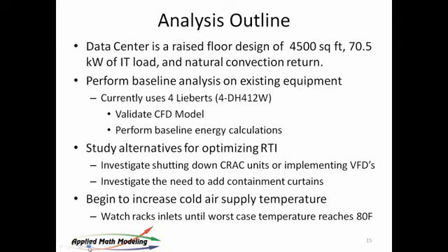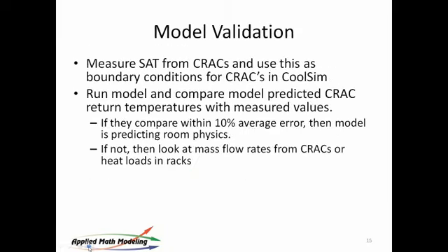The IT manufacturer will tell you, well, that's a 2 kW box, and you put it in and you find it's reading 1.2 or something. So everybody worst cases the situation, and as a result, the optimization, the efficiency of the energy in the room is terrible because it's way off its design curve.